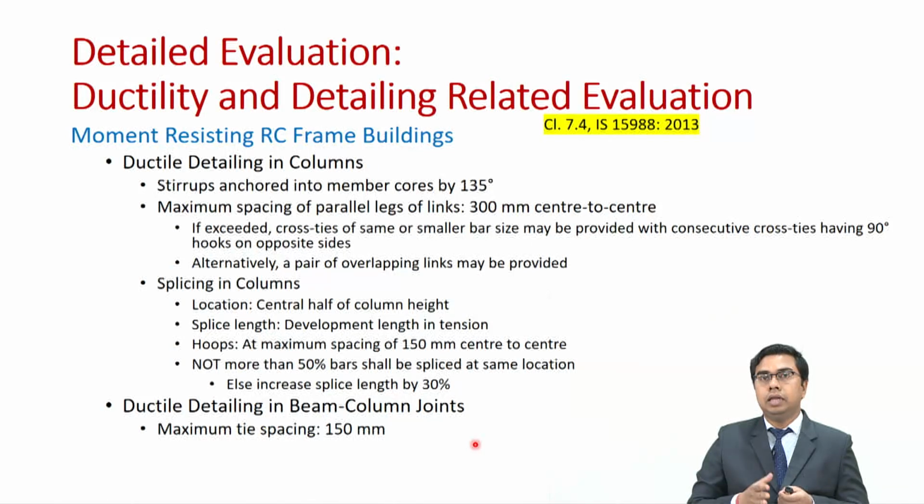And if the building is found to be deficient from this ductile detailing perspective, then we shall use a reduced value of response reduction factor. So we shall have an increased value of demand, and then we can again evaluate whether the building is safe or not when it comes to demand and capacity.